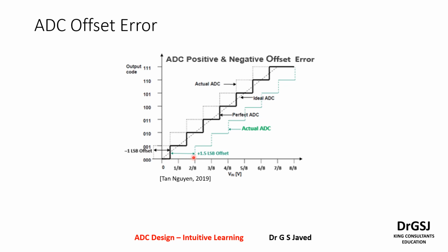So this typically happens in practical scenarios. So it is the duty of the designer to ensure that this offset is corrected and this green graph is moved to the left and the black graph is moved to the right. That way you will try and reduce the offset and ensure that there is better accuracy and less offset error. This is ADC offset error.